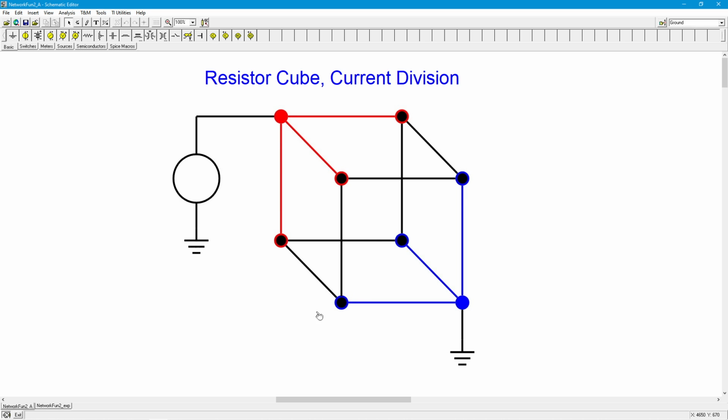And notice at each of these blue and black terminals, you're going to have 2 of the black coming in. Over here it's these 2, and over here it's these 2. So it's going to be 2 plus 2 is 4, which is what we already said as far as the blue is concerned. So if I have 2 milliamps in each one of the black ones, 1K, that's going to be 2 volts. So I should get 4 volts across this, 2 volts across this, 4 volts across this. I should get 10 volts back here. So no matter which way you go, it's going to be red, black, blue. We already figured that out. So it's always going to be 4 plus 2 plus 4. It's always going to be 10 volts.